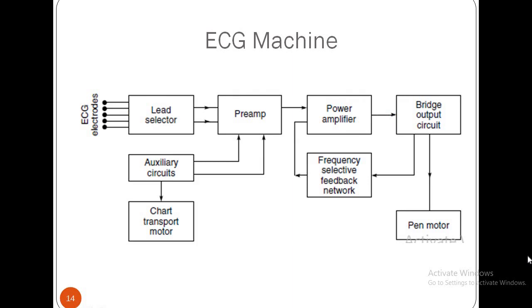The figure shows the block diagram of an electrocardiograph machine. The potentials picked up by the patient electrodes are taken to the lead selector switch. In the lead selector, the electrodes are selected 2 by 2 according to the lead program. By means of capacitive coupling, the signal is connected symmetrically to the long tail pair differential preamplifier. The preamplifier is usually a 3 or 4 stage differential amplifier having a sufficiently large negative current feedback from the end stage to the first stage, which gives a stabilizing effect.